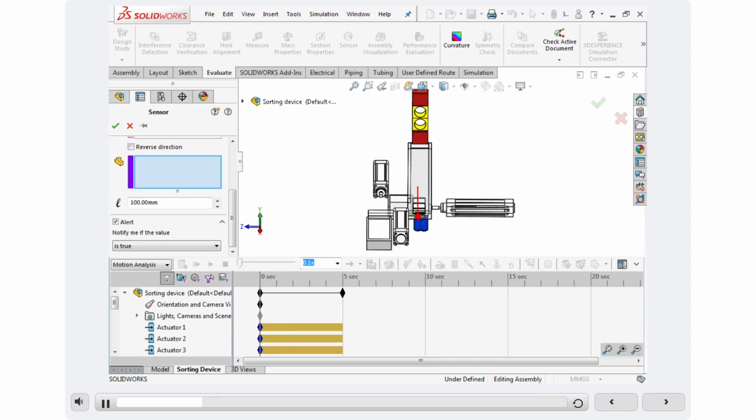Note that you can select them in any order. However, for demonstration purposes, we will select the first solid box for the components to track field. Then, select the second solid box for the components to track field. Enter 12 mm for proximity sensor range. In summary, the sensor will be triggered when a solid block is within 12 mm of the top surface.